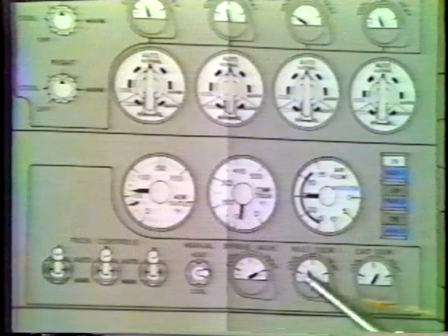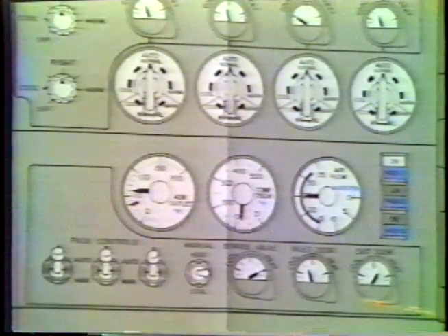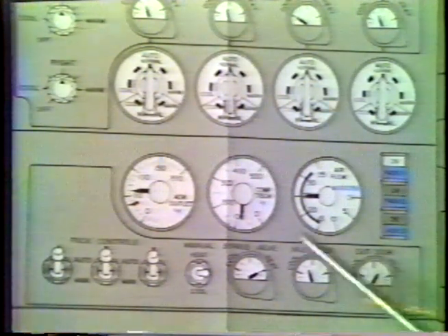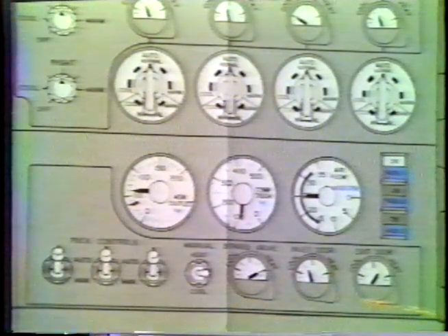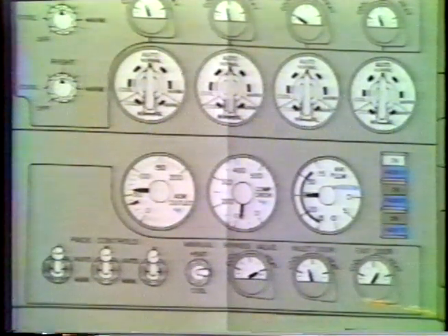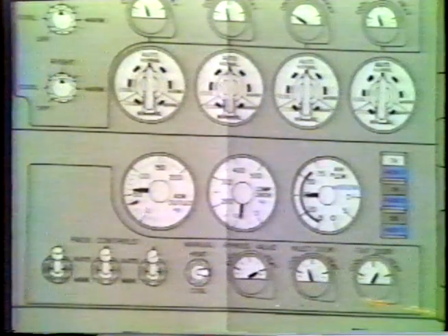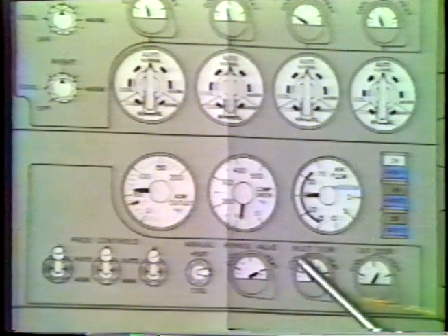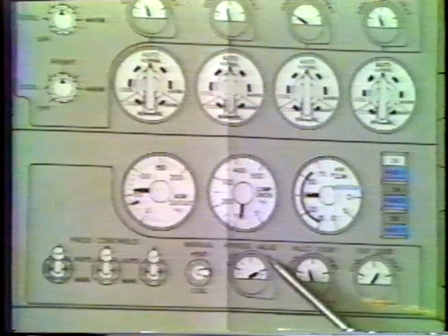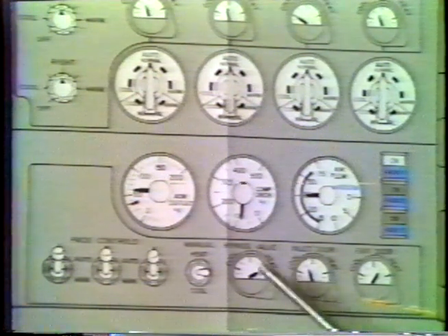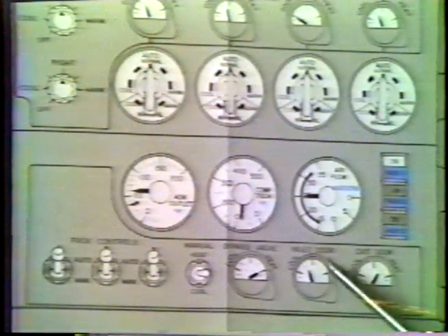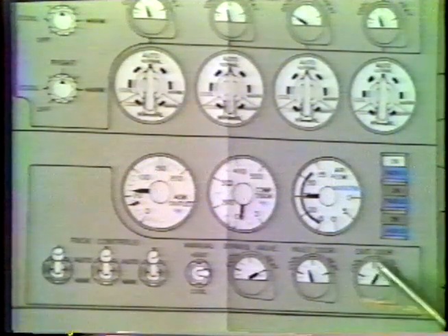The bypass valve controls the amount of air that is going through the air cycle machine. In the cold position, it makes the air cycle machine work harder, supplying cold air, and in the heat position, it bypasses the air cycle machine and allows it to run in the idle mode. Normal operation of the air cycle machine is required mostly on the ground and at low altitudes. At the higher altitudes, the air is bypassed, and the air applied to the passengers and the cockpit is controlled by the inlet and exit door.